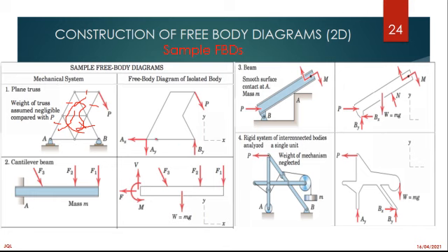Once I do that, where do I have external forces? I have a P, which is the one that I have there. And at the same time, you need to remember the reactions. What type of reaction? When I look at that, that is a pin. So a pin will always have two, one horizontal and the other one vertical reaction, which are represented as AX and AY. And when I look at B, that is a roller. If it's a roller, I know there's only one vertical force, which is represented as BY.